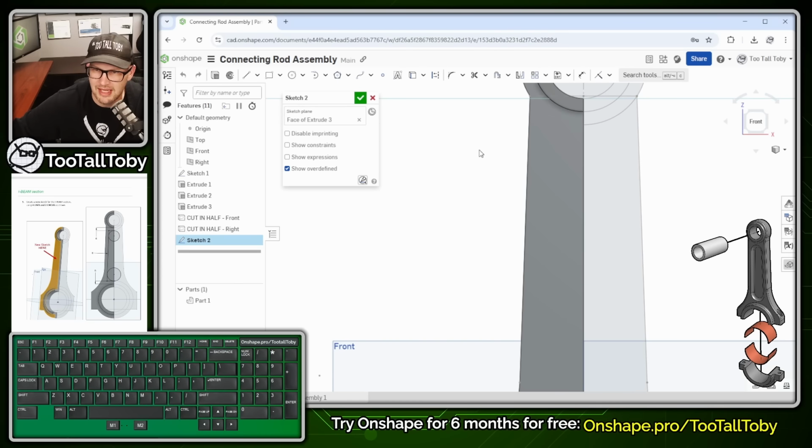So when it comes to sketching these lines, let's press the S key, line. We're going to single click here right in the middle. We're going to make sure that we're coming off horizontal from that middle area, so you see that white horizontal indicator. Now we're going to create a line which is parallel to that side line of the part. What you can do is put your mouse over that side line first to wake it up. And then when you get close to parallel, you'll see Onshape will snap to parallel and it gives you that nice orange preview. So that's exactly what we want there.